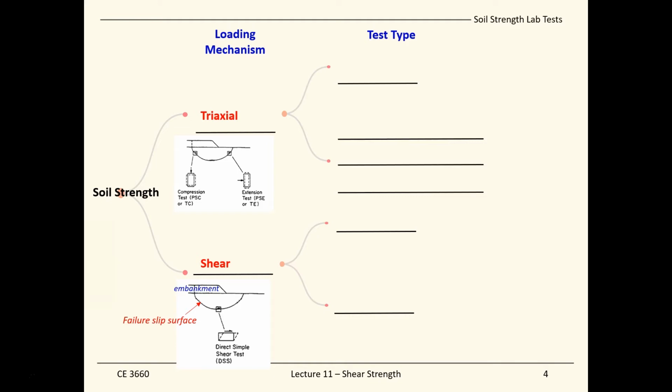Within triaxial testing, there are different types. Understanding all these different types of testing will help us understand the topic of soil strength, and also helps you understand how the business of geotechnical engineering is conducted on a daily basis. So, the different types of triaxial tests. The simplest one is the unconfined compression test, which we'll cover in this class, and also in the geotechnical lab class, where it will be the lab exercise that you'll be working on too.